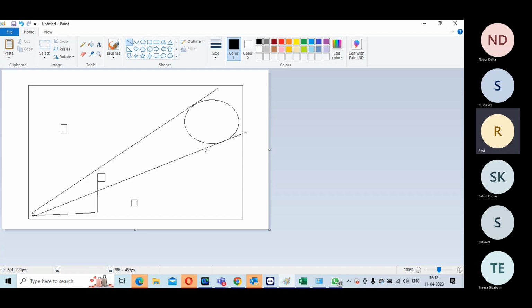And if you are seeing one bunch over here, one bunch over here, clock getting max fan out, you keep it like 32, same standard. If it is more than that, you clone the clock. Driving more than that would be a problem because your clock gate delay will be high. Then you won't be able to do your skewing or anything that is required, and you can end up with a problem. Check that out.